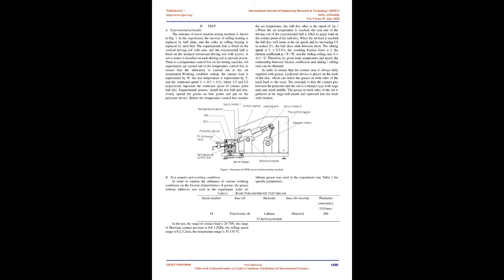constant sliding/rolling ratio, while the sliding/rolling ratio of lubricating grease changed from time to time during the operation of bearing. Most of the above experiments are carried out under the condition of lack of grease, which is closer to the actual working condition of the bearing. However, at present, there is no consensus on the mechanism of grease film forming process and the effect of grease composition on the lubrication performance at home and abroad.